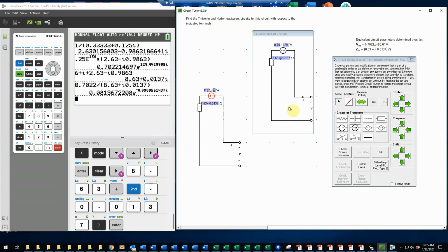And the angle is very small. It's negative 0.091 degrees. Okay, and then I also need to put this in parallel with that current source now. So I'll drag it down here, and then I'm just going to add an extra wire. This may not look like the way we normally draw a Norton source, but of course it is equivalent because I have them both connected in parallel with the output. So that should be fine. I've got the polarity correct, and I believe everything should be good.